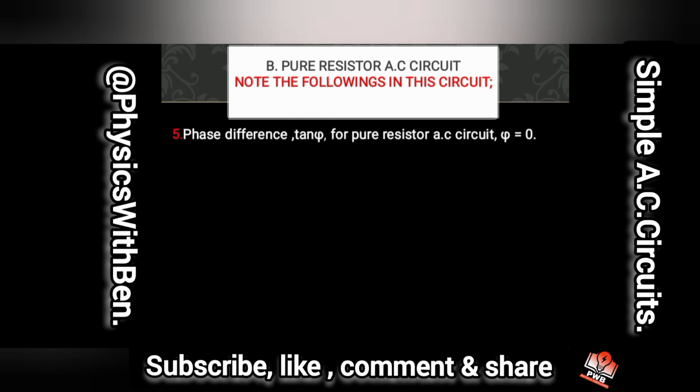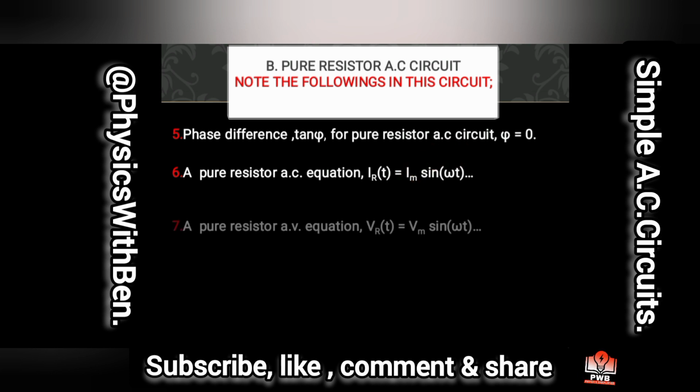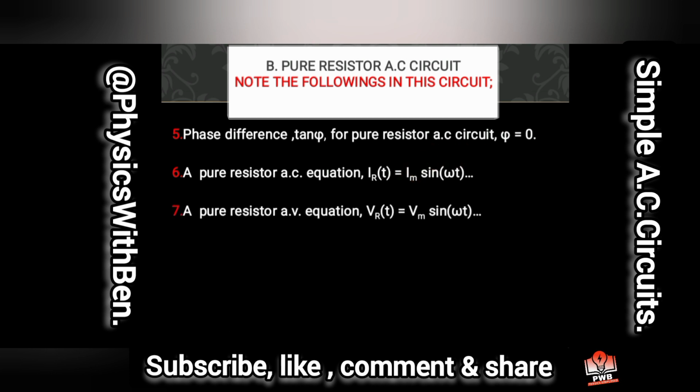Next up, they may ask you to find the phase difference. The phase difference in this particular circuit is always equal to 0, as you can see it here. A pure resistor AC equation is what you just see here right now. Because the phase difference is 0, this equation, I as a function of t equals Im sine of omega t plus negative phi. So since phi is equal to 0, the equation will shrink to this form. And this is a pure resistor AC alternating voltage equation. This is it here.